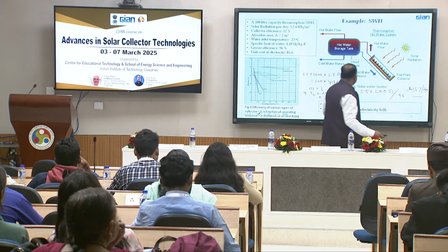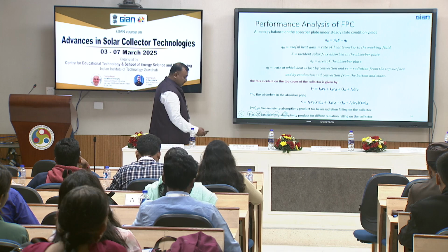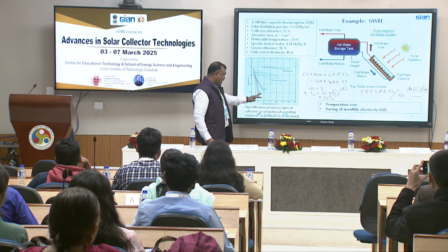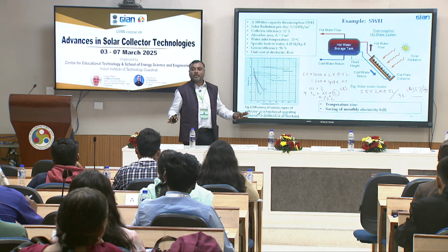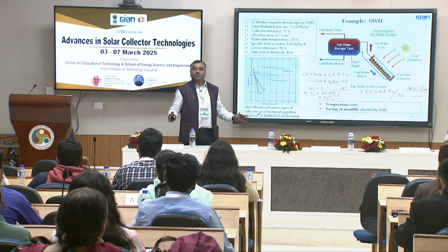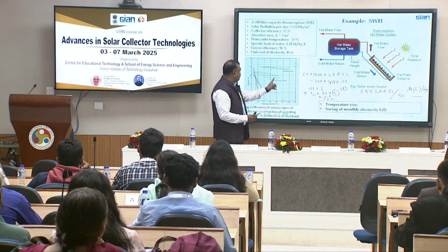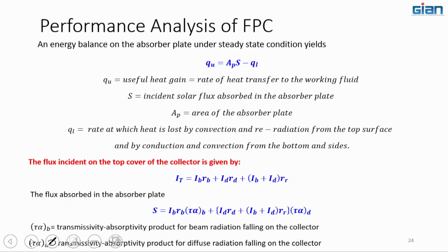So this is quite practical, and you can find out these parameters. And also you can verify. There is a search already people have prepared, showing how this will behave. Sometimes if you don't know anything, but you want the solution, what kind of technology you are going to use if you have a temperature of 400 degrees Celsius. So you just go and see where there is a cross section, then you can find out what the efficiency is and what technology you can use, okay. It's a very useful guide for choosing the right collector at the right temperature.